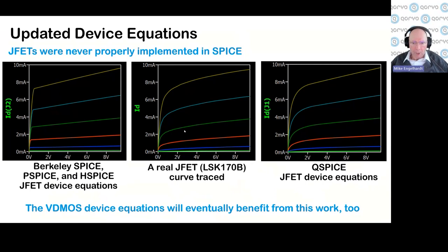And you have to use a pulse test. You can't have self-heating, because even in this tiny transistor, there's a little bit of self-heating you can see. If you look at this top curve, it's bowed down a little bit. That's physically impossible for a JFET to behave like that unless it's changing temperature. This curve should be straight or start avalanching or have impact ionization conductivity modes. It should be curved the other way if it's not straight, but it's curved down. I'm getting some self-heating. So even though I'm doing 100 microsecond pulses every quarter of a second, I'm still getting some self-heating that's impacting this.